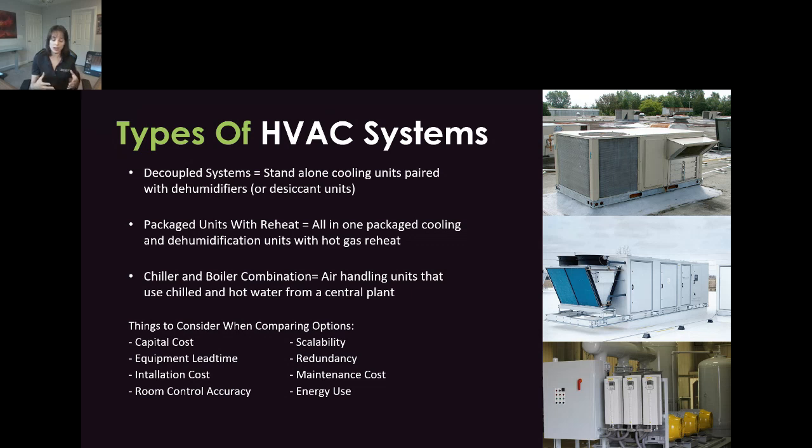So that air, once it is cooled and dehumidified, can then be brought back up to appropriate room space temperatures and put back into your facility. So you're not overcooling a space because you're trying to do the dehumidification. These units are typically more expensive than the decoupled units, but you're going to have an engineered system that has tighter controls in your facility.